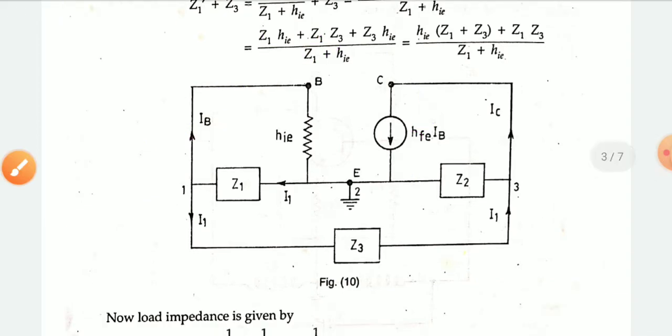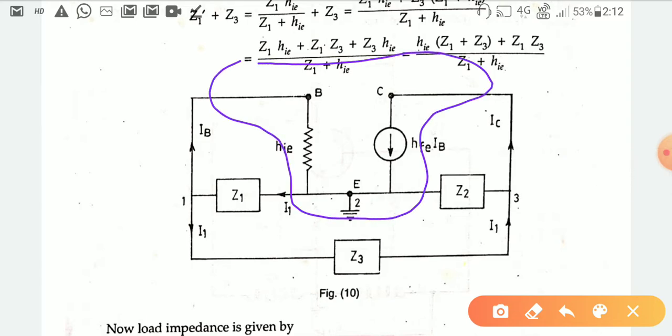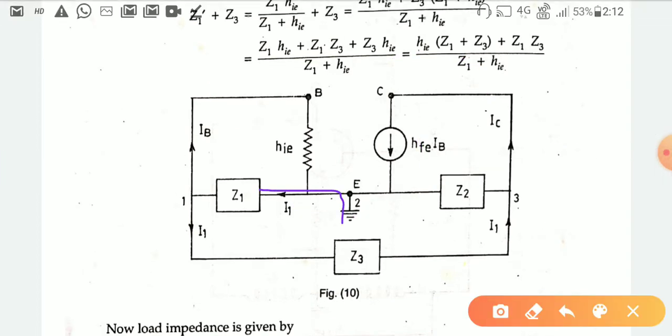And ultimately, due to this assumption, the equivalent circuit for the voltage divider looks like this. There the L1, which is replaced in the form of Z1, has one terminal connected with the ground, and another terminal connected via CB with the base terminal. And the L2, which is written here as Z2, has one terminal connected with the ground and another terminal connected via CC with the collector side.